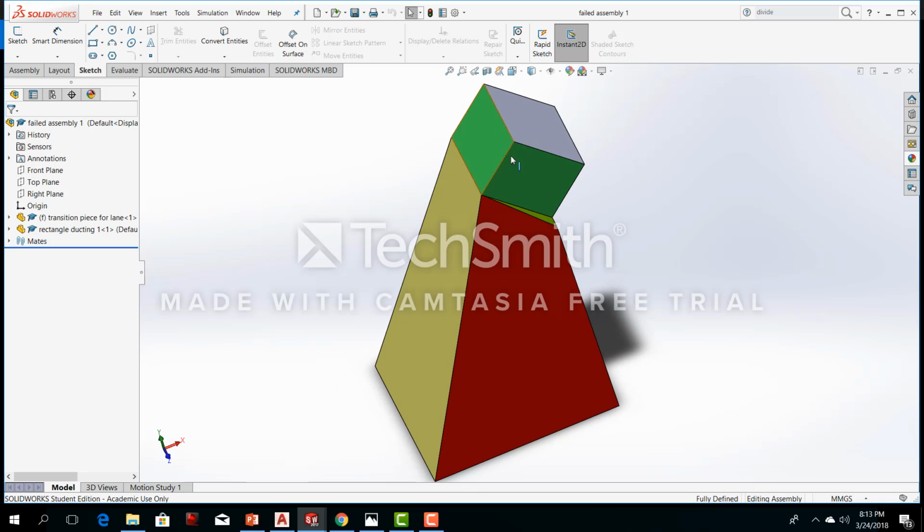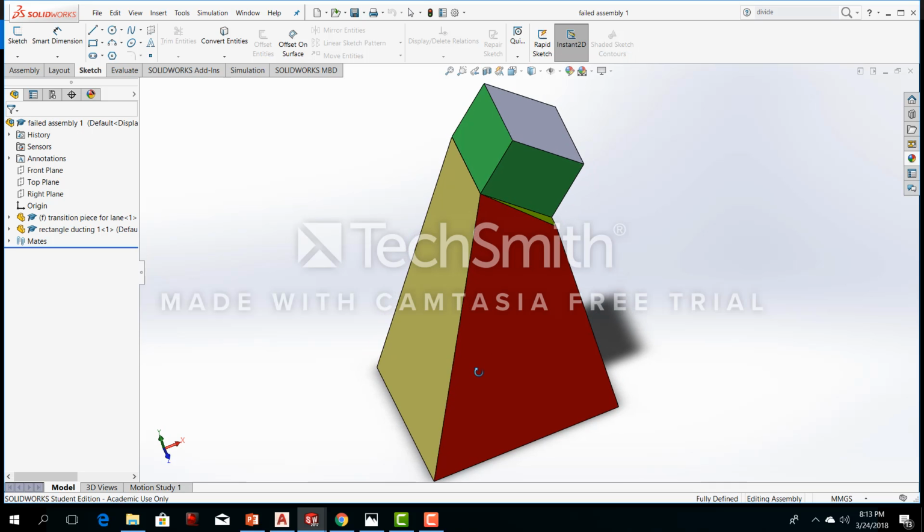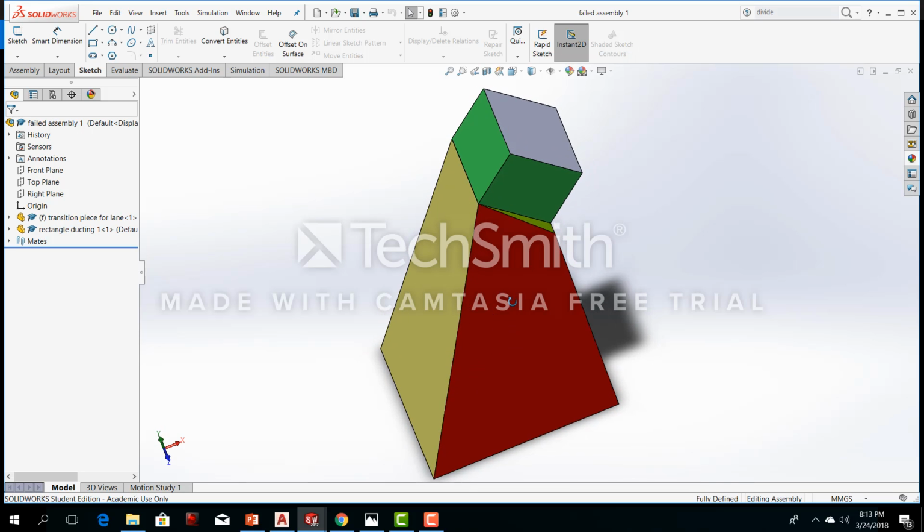So this is our rectangular ducting that we were given, and we're told it's going to intersect with our transition piece. This is the transition piece that is drawn by Anderson, and we treat this as a surface. So we can see here that this triangle that's formed will actually be a gap. So we can explain to students, say if this was a duct letting water down a chute for your gutter, relating it to construction, or if it was an air vent, there'd be air coming out through this, maybe blowing dirty air back into a room if we're relating to the mechanical heat recovery system in construction.